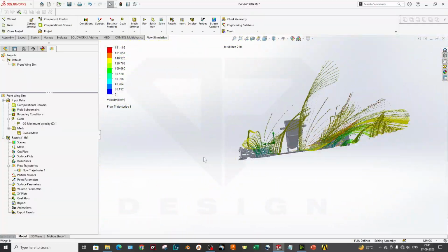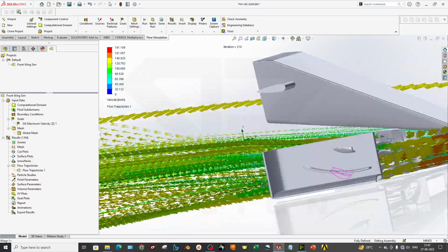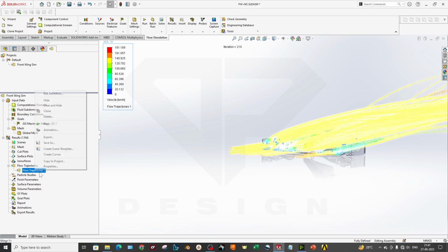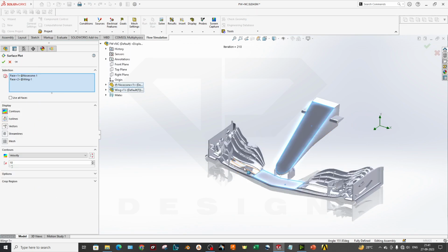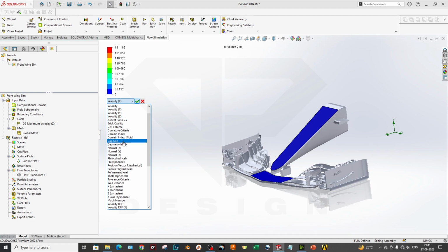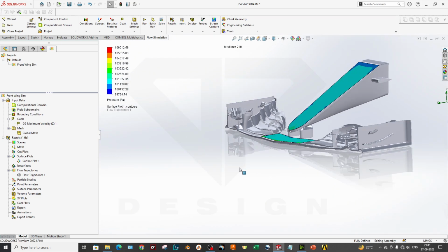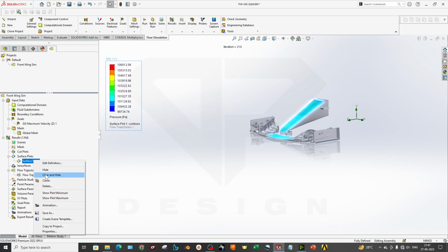As you can see, we have the turbulence over here. It is clearly showing your flow direction. How is your flow going, right? So this is how you can interpret your result. Also, you can go to the surface plot and see what is happening on your surfaces. You can click on it, and velocity will be 0, obviously. You can select the pressure value. So yeah, a pressure difference is there on the surfaces. This is the legend where you can see what values are coming.